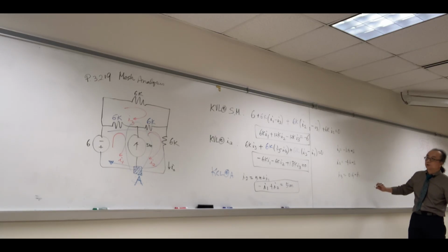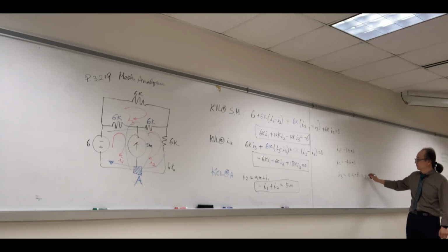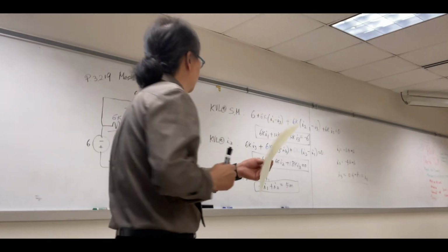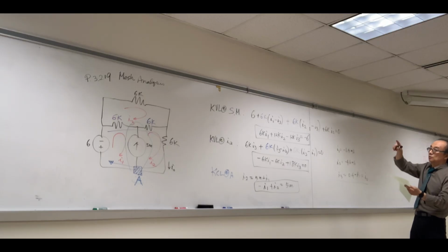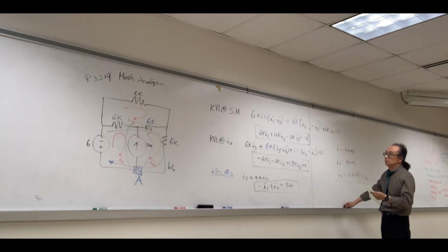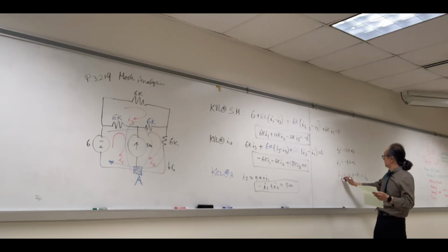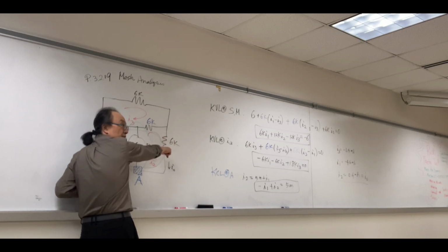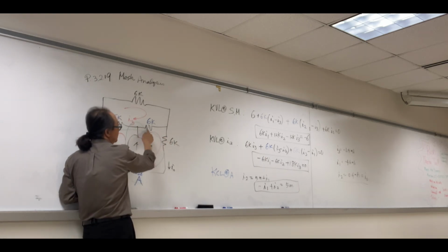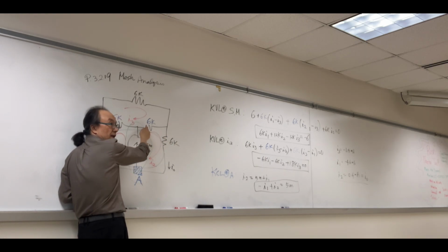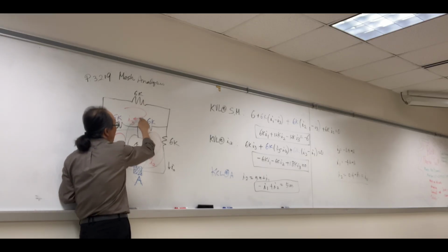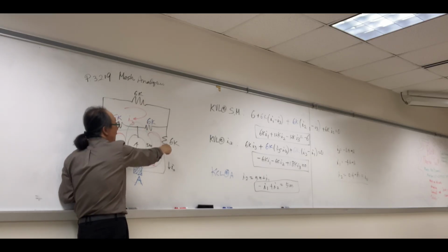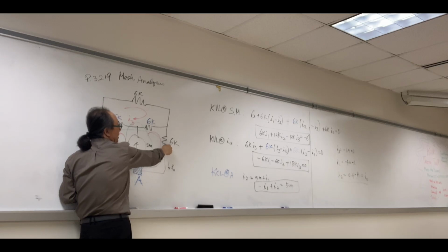And then I sub 0 equals I sub 3. I'm sorry, I used different directions. Sorry, this is I sub 1. So this should be I sub 3, this should be I sub 1, and this should be I sub 2. Yeah, I naught is outside with the 6K. This mesh current I sub 2 is not the current going through this 6K because there is I sub 2 and I sub 3 in opposite directions. However, for this outer 6K, the only current going through is I sub 2.